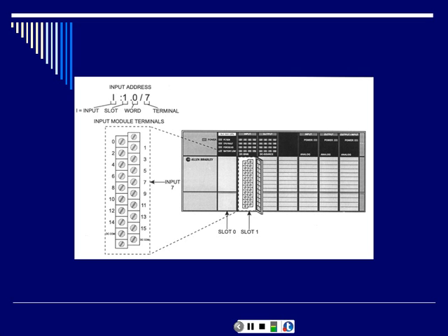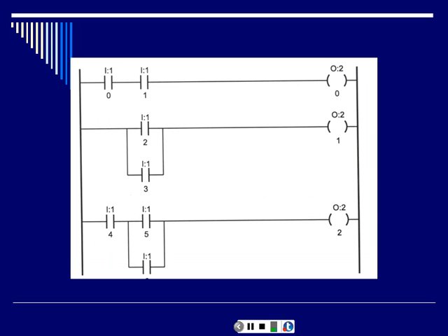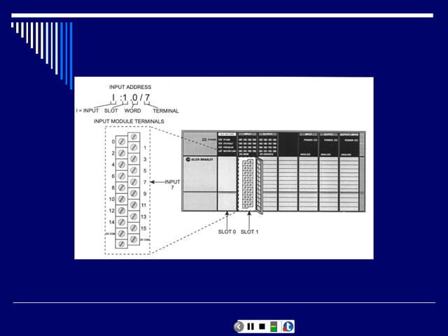It's in slot 1. Everything in PLC starts with 0. So 0, 1. It's in slot 1. The very first screw that I can attach to is 0. So input, slot 1, screw 0. Everybody okay? So if this were my PLC, it would be wired right there. And it would be wired down to DC voltage right here, which you probably can't see, but that's the screw that says DC voltage. Okay?